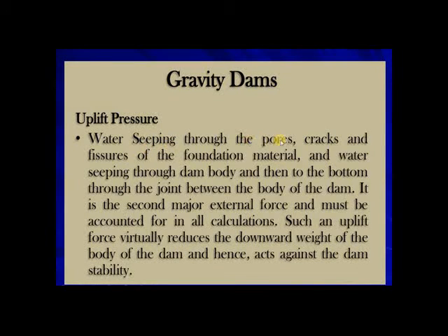Water seeps through the pores on the upstream side, cracks and fissures of the foundation material, and through the dam body and then to the bottom through the joints between the body of the dam. It is the second major external force after the water pressure and must be accounted for in all calculations, as an uplift force vertically reduces the downward weight of the body.